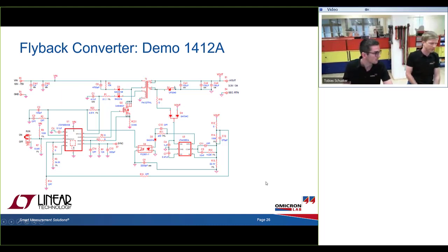There is a question, Tobias, that I'm going to read right now. The question is, when you do a calibration of the probes, where do you connect both probes? Is it best to do it on the feedback side or on the output side? And I try to immediately answer that. In my opinion, it's best to do it not in the circuit, but directly on the signal source of the Bode 100, because then you will have a clean signal without any noise and without any disturbances. So I wouldn't do it in the circuit, I would do it out of the circuit directly at the output of the Bode 100. So similarly as you have seen in the picture before, where you can see how to check if the probes need calibration or not. Exactly.